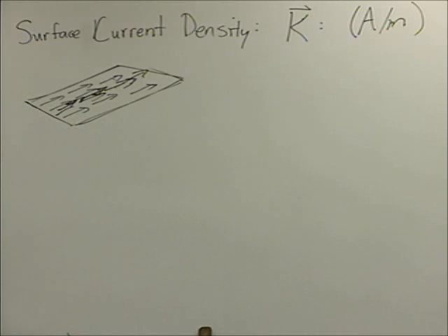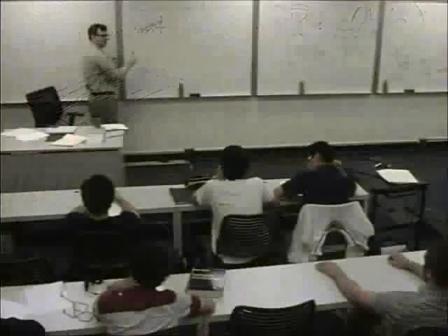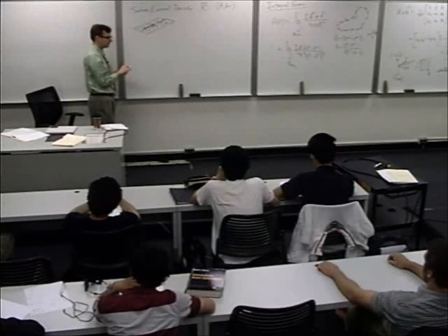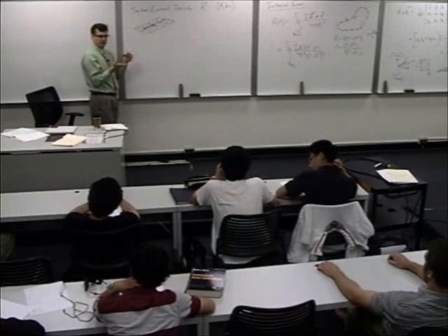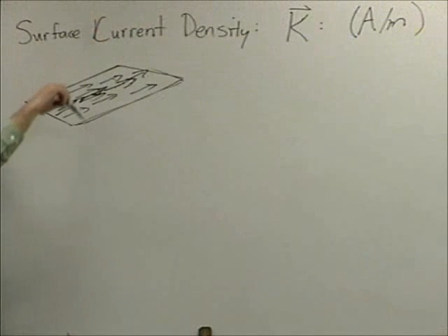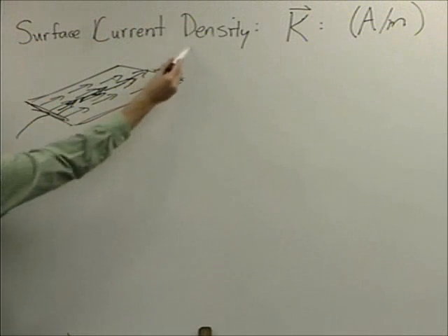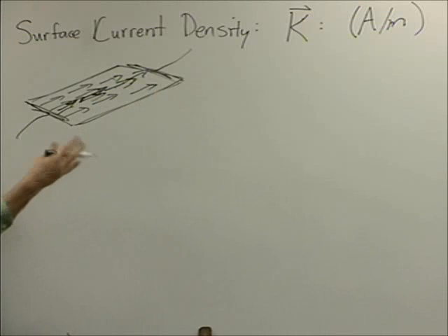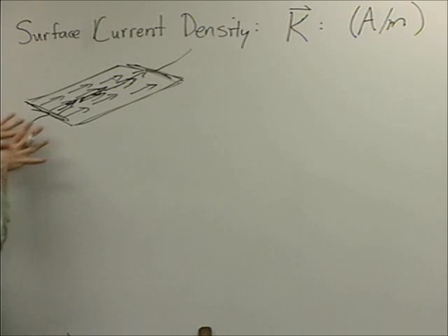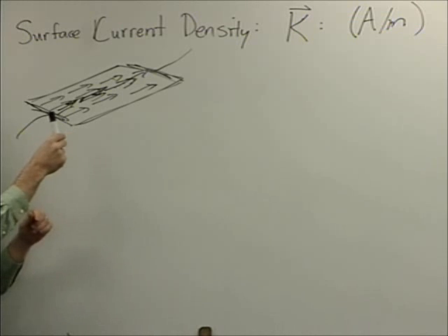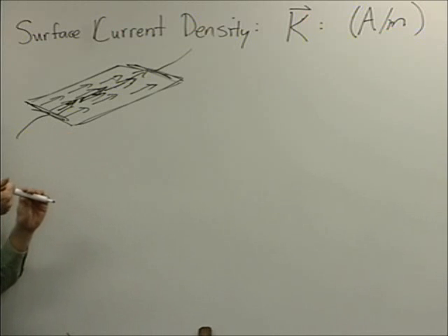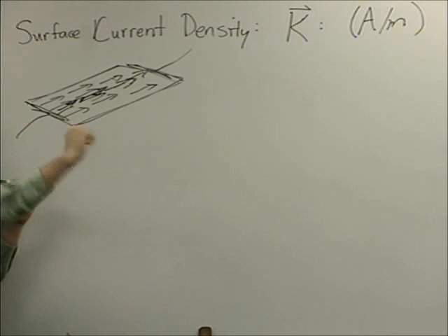The Hall effect sensor is basically if you put a magnetic field on certain thin pieces of metal. What does a magnetic field do, right? If it's perpendicular to this conducting sheet, say you wire this up, and according to our Ohm's law analysis, this should be a nice uniform current being carried in the absence of a magnetic field. But if you do impress a decent-sized magnetic field here, those charges, well, they're electrons, right? So if they're traveling this way, the polarity is actually this way when you go to calculate that v vector. Charge times velocity is pointing this way.